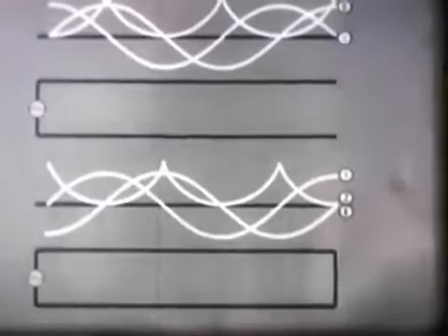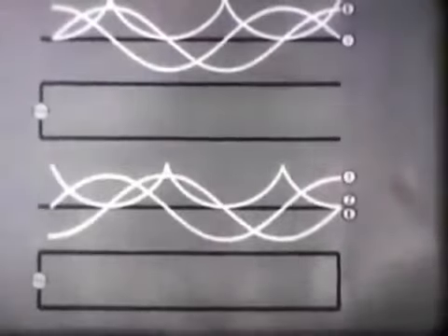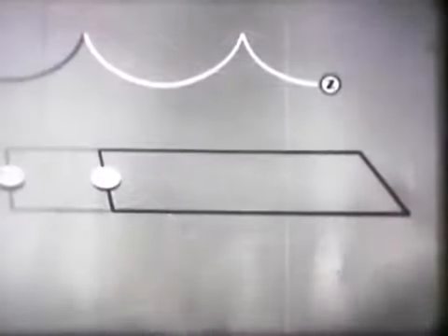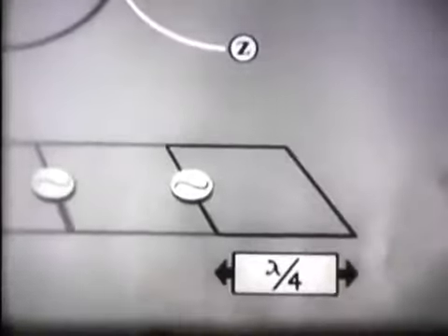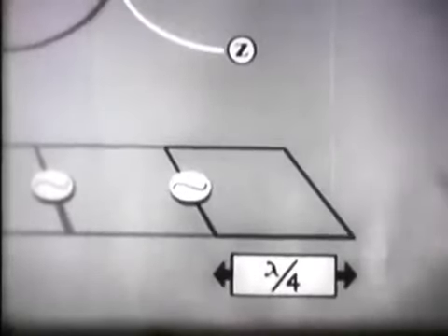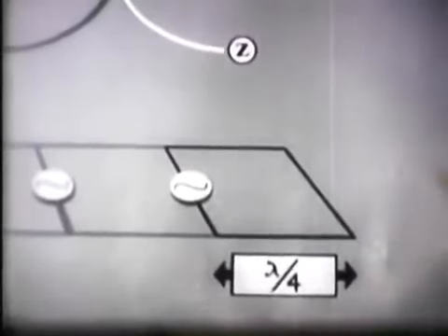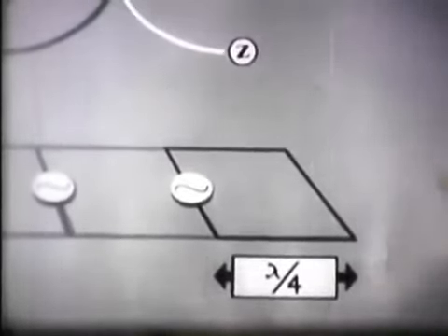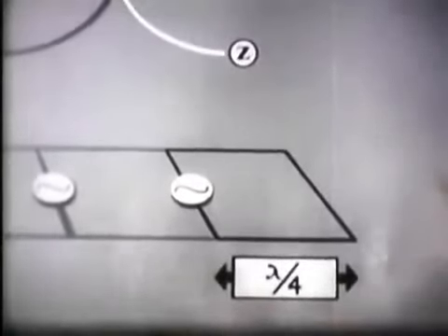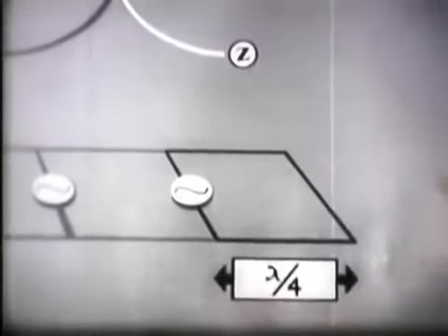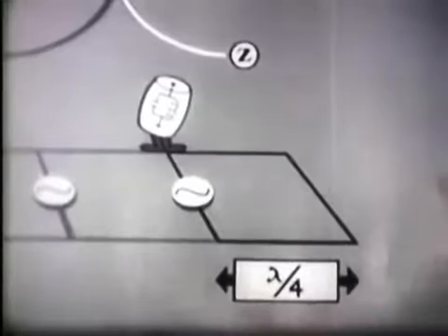How does this apply to radio antennas? Well, let's shorten our closed-end line and find out. Now we are working with only a 1/4 wavelength of a closed transmission line. The impedance at the terminals of the generator is maximum. In other words, the generator sees the circuit as one of maximum impedance. Where a line presents a high impedance to the generator, it is the same to the generator as though it were connected to a parallel resonant circuit. So we can symbolize this 1/4 wavelength line as a parallel resonant circuit.